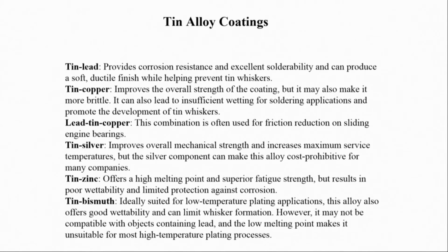One of the biggest problems in developing tin coating by electrodeposition is tin whisker formation. What happens is that if there is surface roughness, at the rougher points there is charge accumulation, as a result of which the amount of coating deposited at that particular point gradually becomes much higher than at other points, and as a result there is a very thin whisker formation.